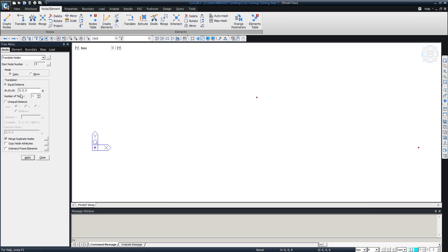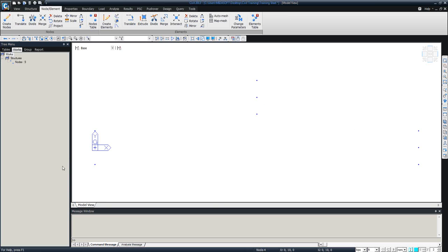In the Y direction, I enter them into X. All right, and then to select them again, here we have only 3 points, but it's good to know there is a function here, select previous. If you click on that, all the elements or nodes that were previously selected would be selected again. So this time we'll go 10 feet downward.